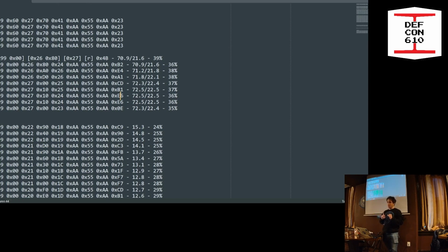I haven't been able to crack this CRC. It's not any of the standard ones. I also brute forced the polynomials, but none came out that works on all the data. So that either means that data is missing, or it just gets modified by the chip.